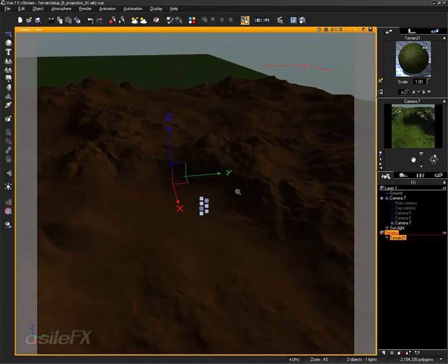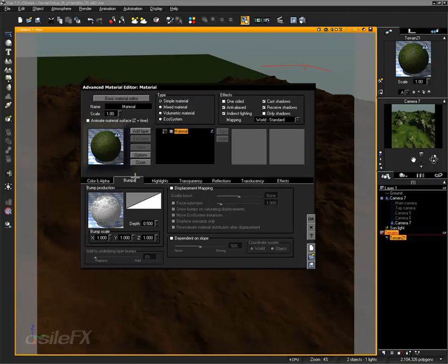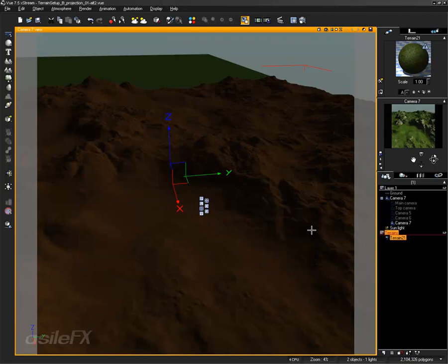It doesn't work like other programs might subdivide. If you're a Cinema 4D user, it would be kind of like a HyperNurbs. That sort of rounding is not available in Vue. What it does is just divide the polygon and keep dividing the polygon. If you have a displacement map set up, so if you go into the material, onto the bump channel, there's also displacement mapping. That will control the subdivision. So that's really the only way to control that subdivision, with the displacement map.